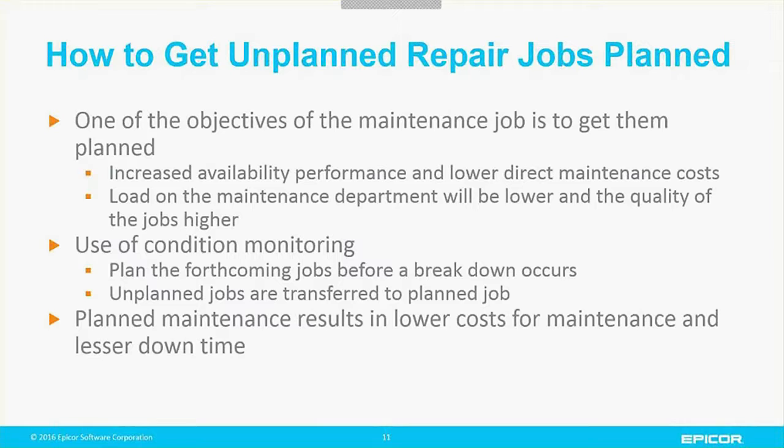The other way of doing it is to look at condition monitoring. If you're running high-speed machines that have a temperature profile or a speed profile, you can look at the rate of production, the temperature of bearings, the energy draw of those machines, and extrapolate when you're going to move outside of a desirable set of parameters and predict when maintenance should be carried out to then bring those pieces of equipment back in.